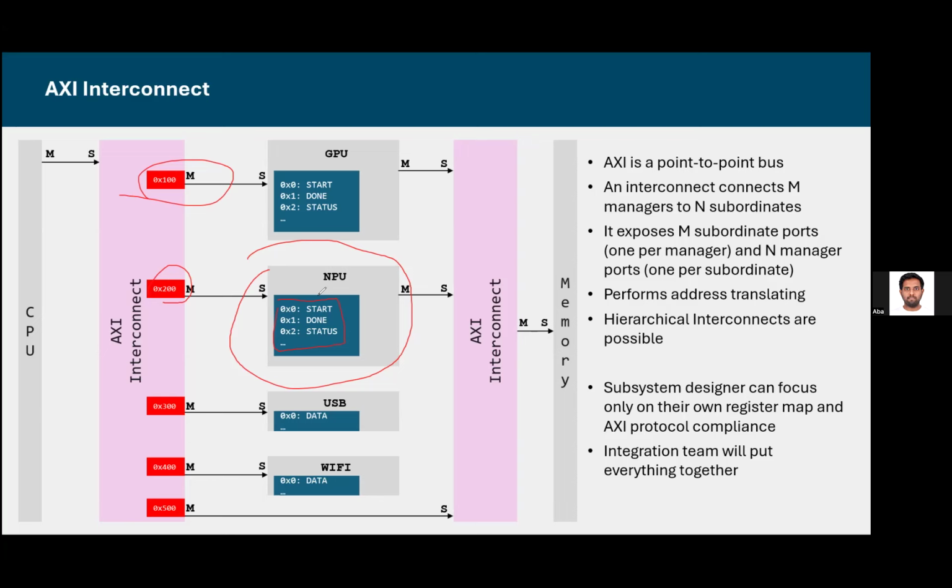Okay, so you want to know how to interface your IP to DDR, right? Unless you are working at a company which does that, you won't be directly talking to DDR. Whatever SoC you are using will have some sort of a thing that talks to the DDR, like a DMA, and you will be talking to that.